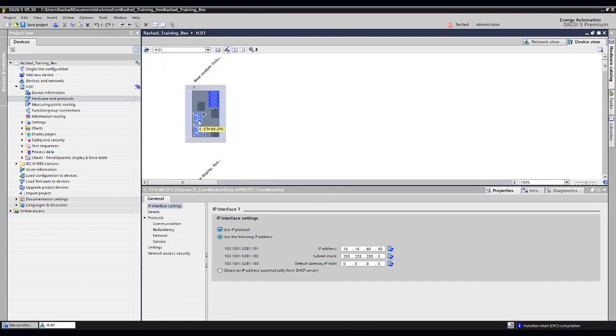And of course, if I had it, I would have the protection interface where you place the device address and remote device address. And then we start adjusting the configuration and choose whether I have direct fiber or a media converter and what my baud rate is and so on.